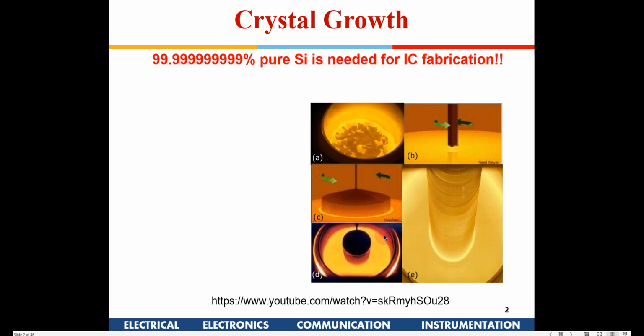So pure silicon is taken and put into a furnace. It is melted, and then you have a small seed that is inserted into the furnace, and by slowly rotating, you pull it up. Once you slowly rotate and pull, something known as an ingot comes up like this. So this is the first step.